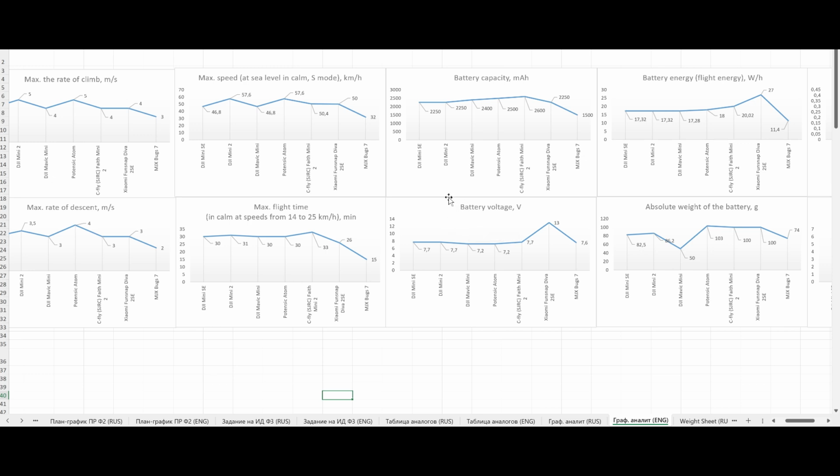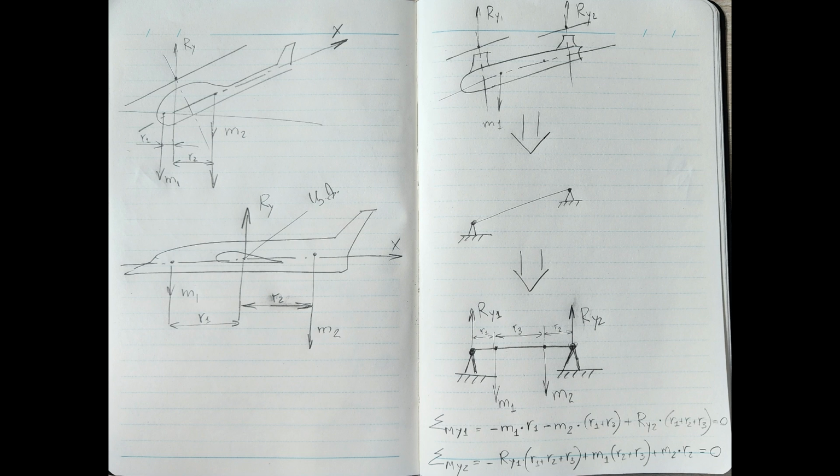In addition, the reasons for deviations from statistical weight formulas for a new generation of UAVs may be changes in the applied technological processes, such as reduction of thickness during injection molding. The second, changes in the list of used structural materials. Third, change in the strength standards and the safety requirements for UAV flights. And the last, changes in environmental standards, etc.